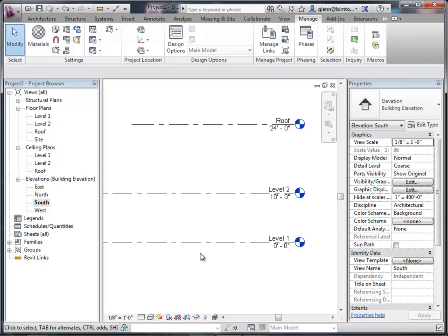It gives you a lot more control, because if any of the parameters change, the wall will change with it. So in general, having good levels set up as a starting point is good, but then as we go through, always hinge things against levels whenever we can, or other parameters. It's much more powerful. It's all about managing things by constraints as opposed to explicit numbers, and it gives you a lot more power in the long run for redesign. Okay, so you got some levels to work with? You feeling good there? If you've got levels, let's go ahead and start creating some walls.